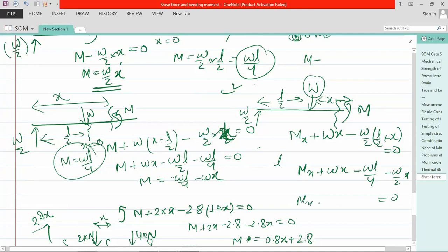Now, sorry, Mx plus Wx by 2 minus WL by 4 is equal to 0. Mx is equal to WL by 4 minus Wx by 2. Now I am getting it right. Okay. Now, are you getting it? The question was. Yes, sir. Clear, sir. Now this is the value, and now if you put x equal to L by 2, it will be equal to 0. Okay.